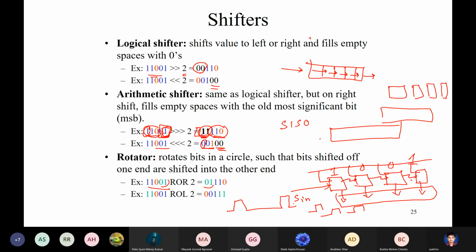Okay, so usually what is done, you can easily design the logic. I'm not designing the logic. You have another line which is called write shift. In fact, there's another line called write bar shift. So this is one additional line you have to this entire thing. When this write shift line is 0, write shift control is 0, then the value is written. Parallelly the values are written. And when this write shift line is 1, the values are shifted.